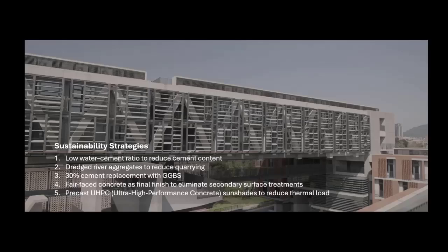Sustainability strategies: low water cement ratio to reduce cement content, dredged river aggregate to reduce carbon, 30% cement replacement with GGBS, fair-face concrete as a final finish to eliminate secondary surface treatments, precast UHPC sunshade to reduce thermal load.